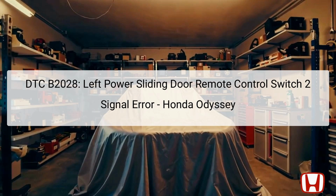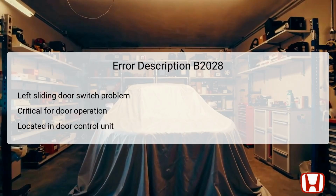The troubleshooting process involves systematic checks using the Honda Diagnostic System, HDS, to identify and resolve the underlying problem. The B2028 code signifies a specific malfunction related to the left power sliding door's remote control switch. This switch is designed to facilitate the automated opening and closing of the sliding door, a feature that greatly enhances usability, especially in family-oriented vehicles.